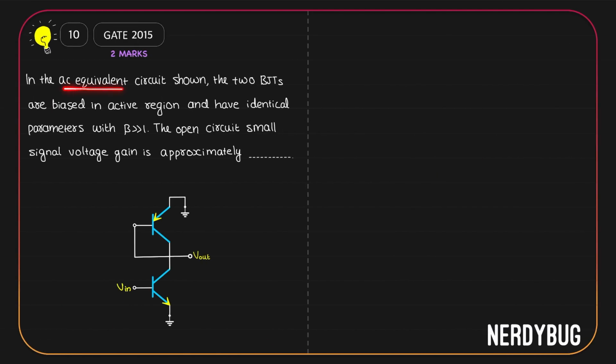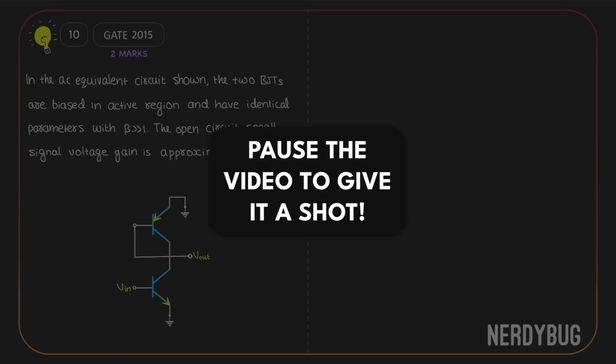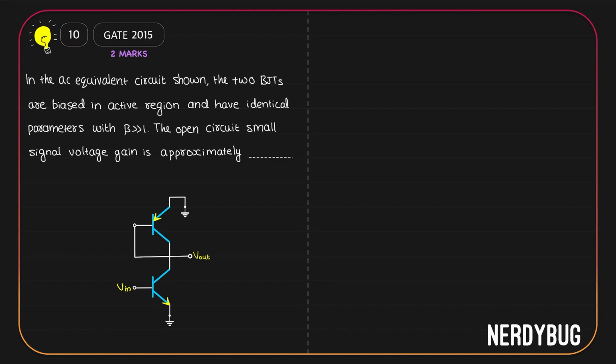In the AC equivalent circuit shown, two BJTs are biased in active region and they have identical parameters with their current gain being very much greater than 1. What we have to find out is the open circuit small signal voltage gain. The first and the most important thing, do you see anything familiar in this circuit? What we have over here is a transistor whose base and collector are shorted. It is a diode connected load.